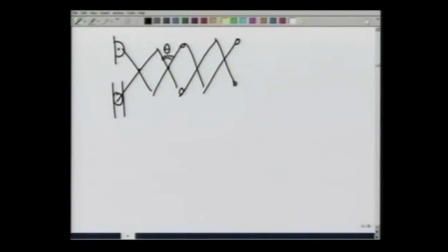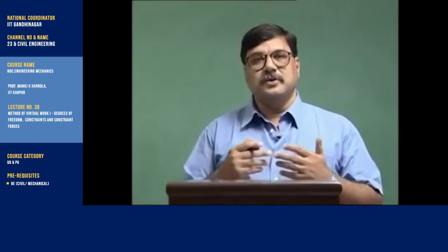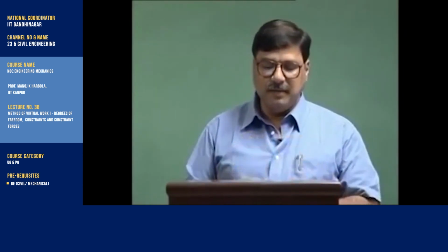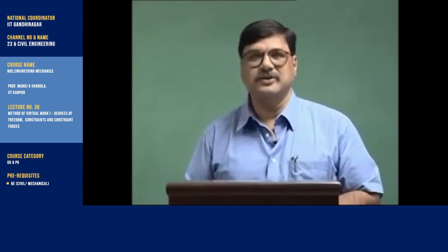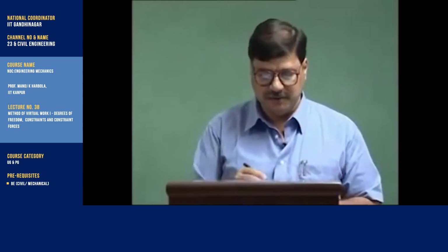Nothing else. The moment I specify this theta, because the lengths of these bars are fixed, I specify exactly how the system is. So degrees of freedom in this case is also 1. So this is one concept we are going to use. The degree of freedom specifies the parameters used to describe a system and the complexity of the problem. The fewer the degrees of freedom, the less complex the system is.